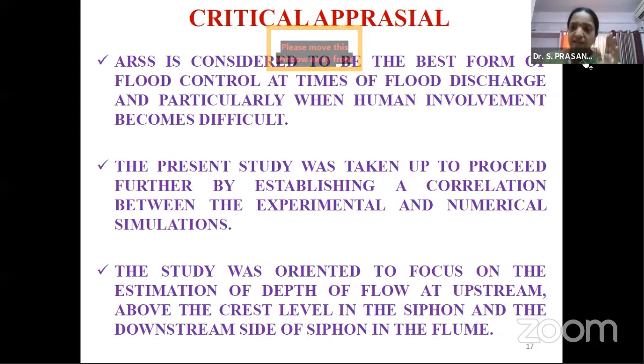You use it, then probably you can compare those results using K omega also. Because the same model you apply, you just change the model type there. That's all. You can use both. Nothing is inferior or superior to the other. Commonly, widely adopted is the K epsilon model.